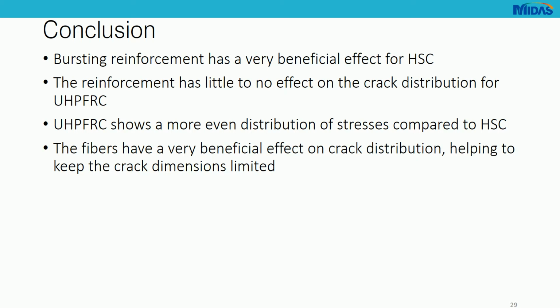Now, to conclude, from the test that we've carried out, we can see that the bursting reinforcement has a very beneficial effect on high strength concrete. For the case that we've considered, without the reinforcement, the high strength concrete couldn't take the entire load. Whereas when we consider the ultra high performance concrete, the reinforcement had little to no effect in both the stress levels and the crack distribution.